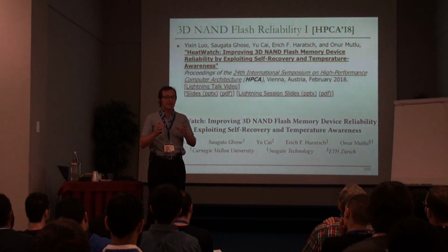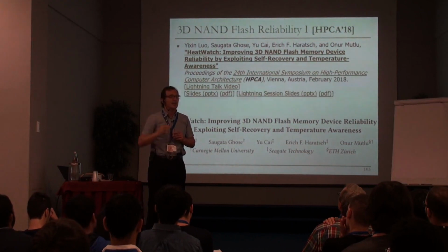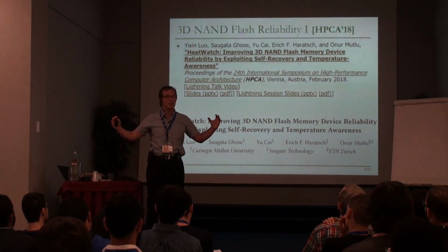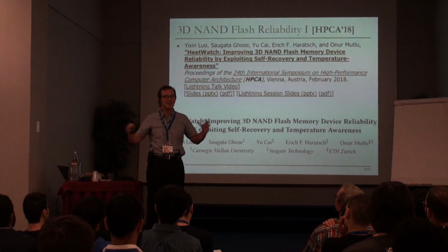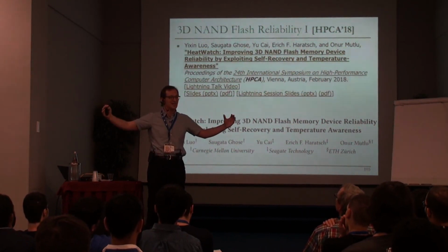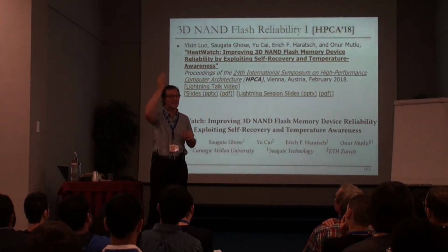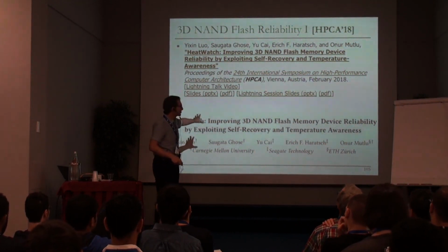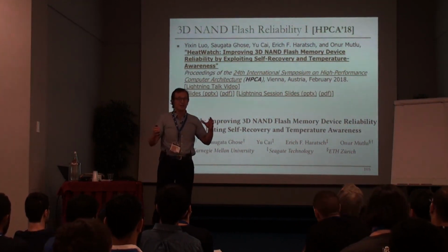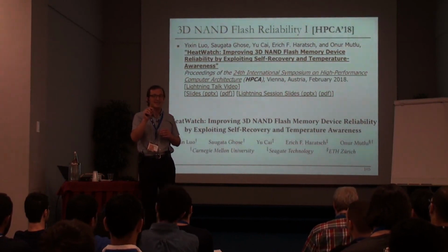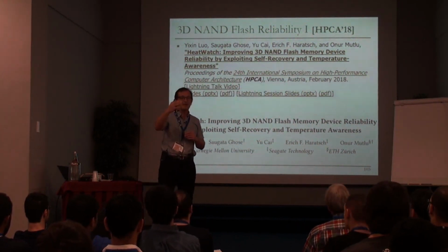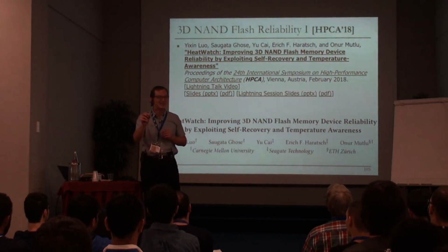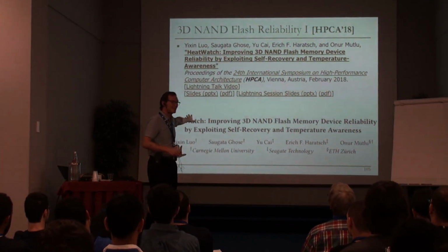What they did was they were able to gain more capacity by vertically stacking, and they didn't need as small transistors anymore to get the same capacity. So they increased the size of the flash transistors, but they stacked more layers. As a result, they got higher capacity, higher reliability at the same time. So that's beautiful. But there are some other issues also over here. But it turns out if you can find a technology like this that can get you higher capacity and higher reliability at the same time, you should always take it and invest in it. And that's what happened in 3D NAND technology.